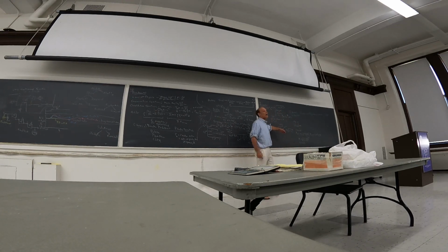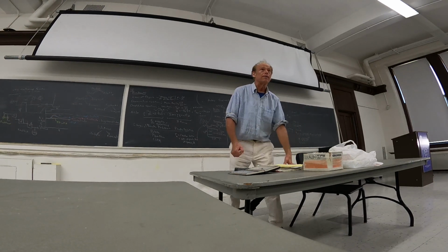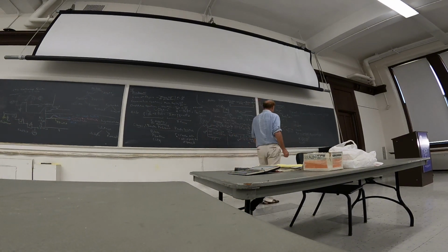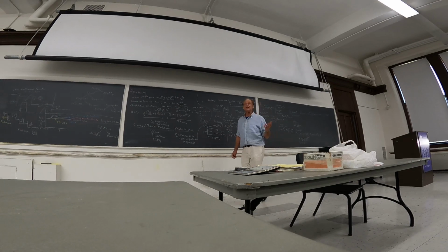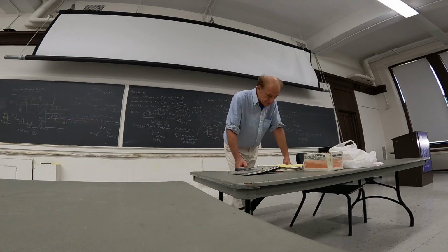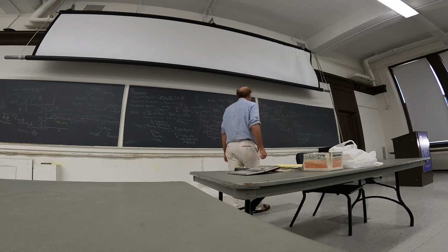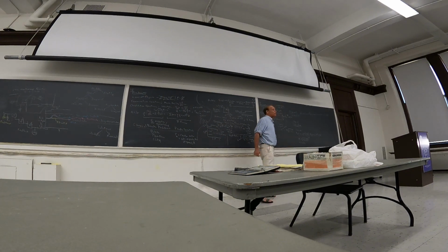So this is an example of if I have a tank and I have a little pipe here with the fluid coming out, and I want to estimate the flow rate through gravity, I would just estimate the out volumetric flow rate is proportional to the square root of L1 minus L0. So those are possibilities. Are there any questions on that? A lot of times your book just gives you an equation like this without telling you where it comes from. It's easy enough to tell you where it comes from. Okay, so that's an example of an equation for V out.